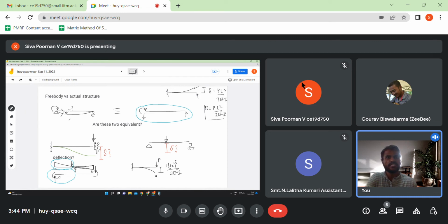So I can easily find out the deflection that is happening in a guided fixed roller. Guided fixed is nothing but two cantilevers. Once I understand this, most of my problems which seem complicated, we can actually compare with the known things and understand them better, and get out of the fear of seeing complicated boundary conditions, right? That is why I wanted to emphasize this.